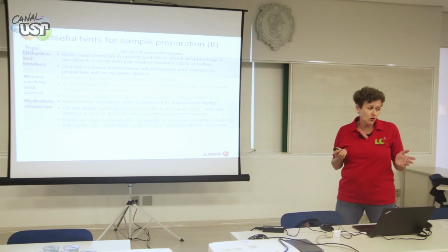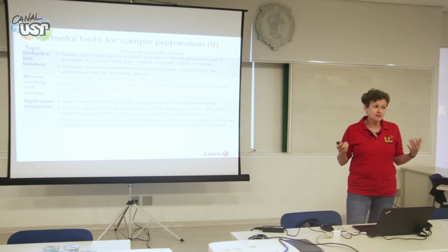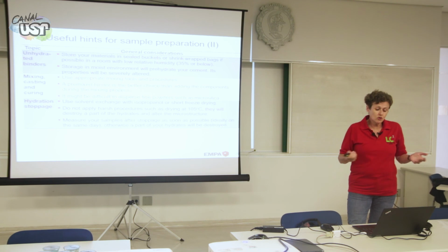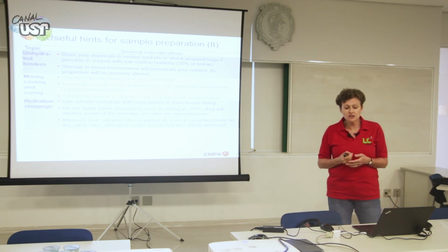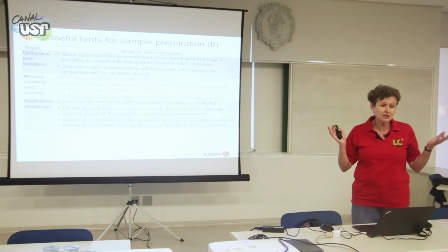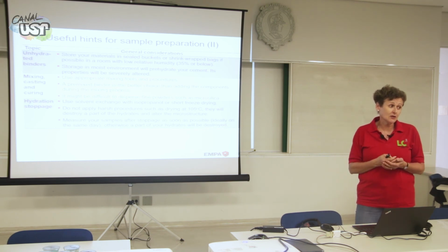I cannot emphasize that enough, because still today, I would say a majority of people submitting papers are still drying at 105. Unfortunately, it's a method that's talked about in a lot of standards. So in many, many countries, there's this method that's supposedly meant to be for assessing the total porosity in a material, where you dry at 105 and resaturate, or you saturate and then dry at 105.